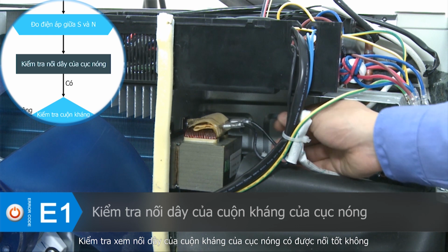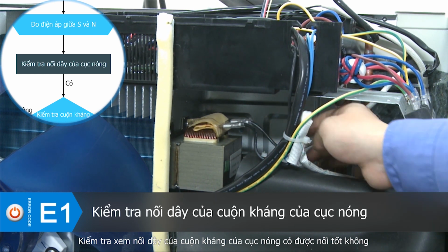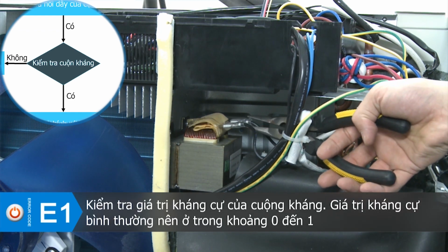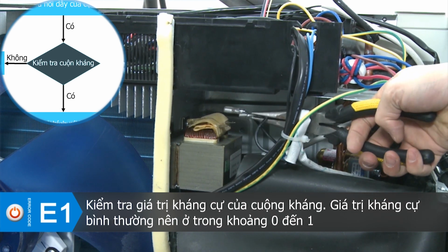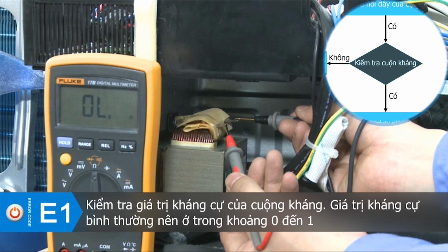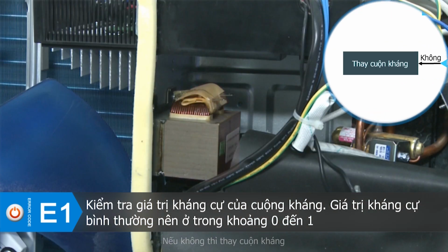Check if the wiring of the electric reactors of the outdoor unit is well connected. Measure the resistance value of the reactor. The normal resistance value should be within the range of 0 to 1 ohm. If not, replace the reactor.